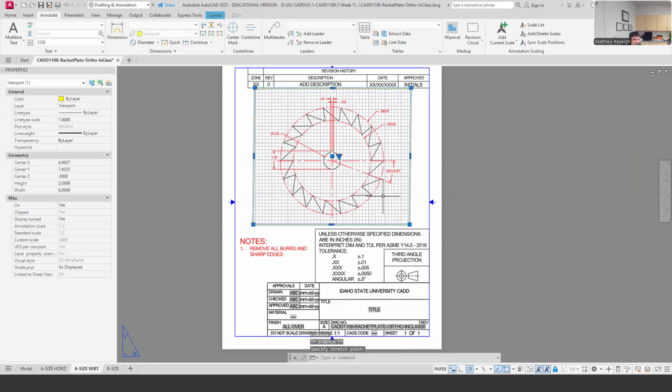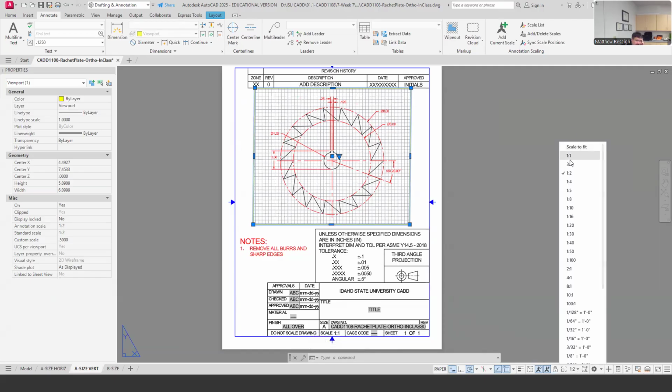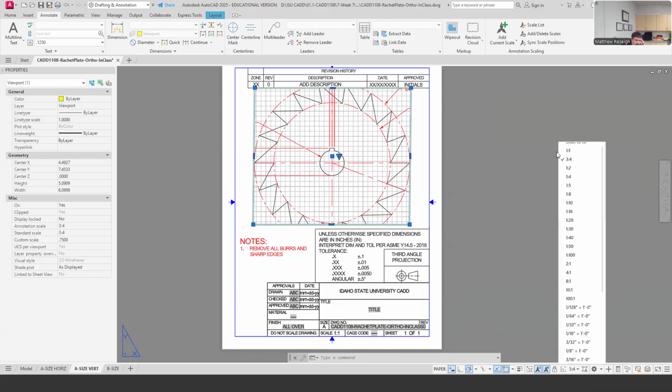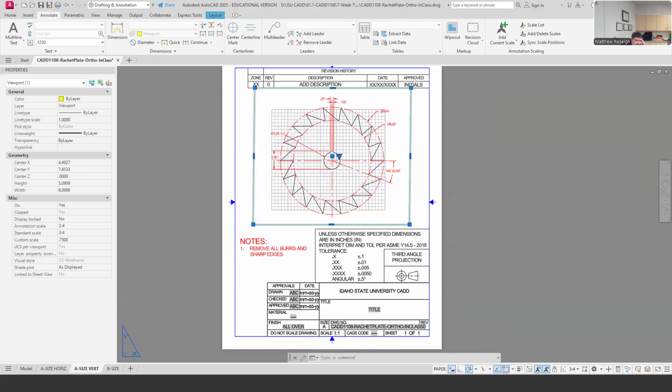These should work good. One thing to note, sometimes if your dimensions act like they haven't adjusted for you, just unlock the viewport and maybe flex this thing and make sure your annotative dimensioning, sorry, let me go back. Annotative dimensioning kind of flexes and pops for you. So sometimes locked viewports won't allow that automation to happen. So just unlock them for a minute, flex them, and then put them back, and then readjust if needed.